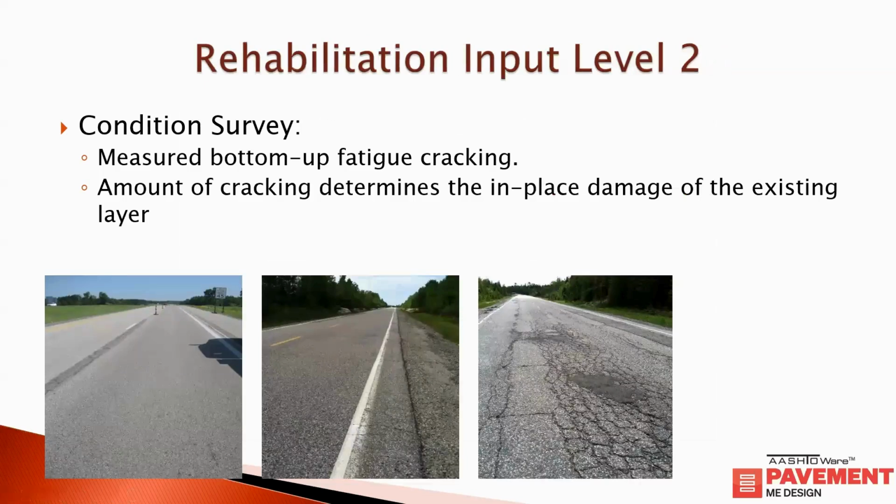Now, once we move into level 2 for rehab, the requirement here is from a condition survey. So you've gone out, you've measured your total lane area cracking, it's measured as bottom up fatigue cracking, and the amount of cracking here determines the in-place damage of that existing layer.